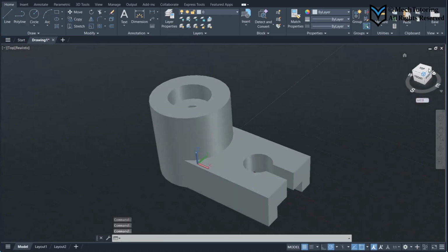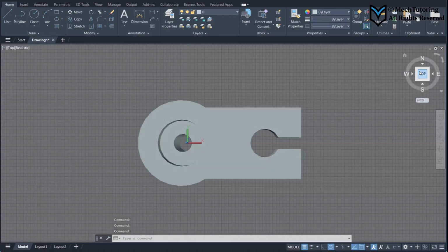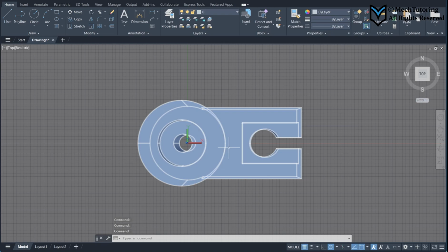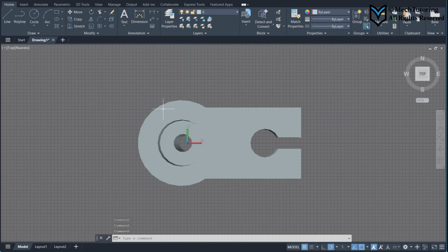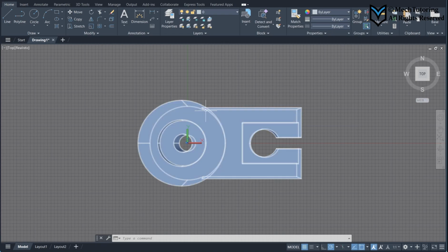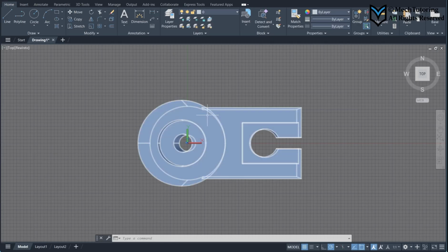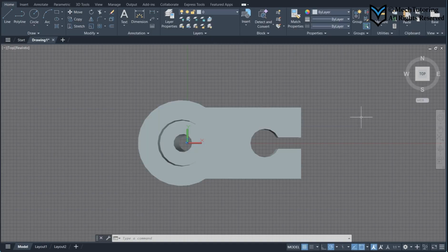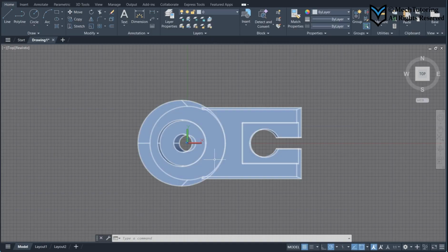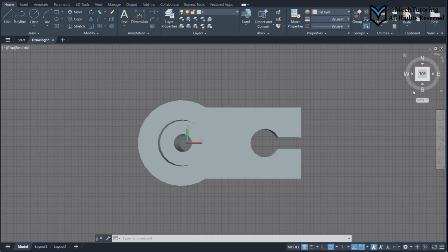Sorry, that in this top, okay. Now it's the top, okay? You see that the top view is kind of like a distorted type of view, okay? It's not actually showing you the top over here. It's a perspective type of view. It's not like an aligned view. So it's really hard to sketch on this surface. It's better to draw the wedge on the side and then move it to this place, okay? Because then the geometry is going to stay completely what we want.